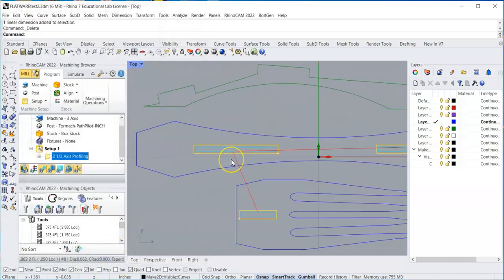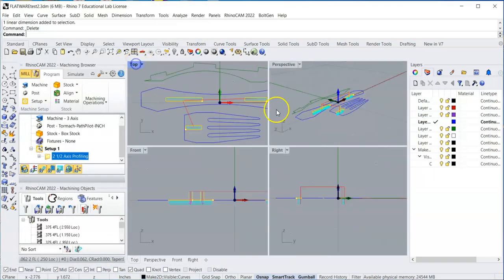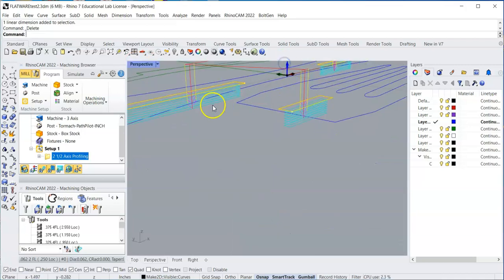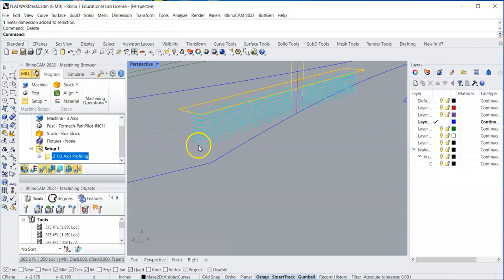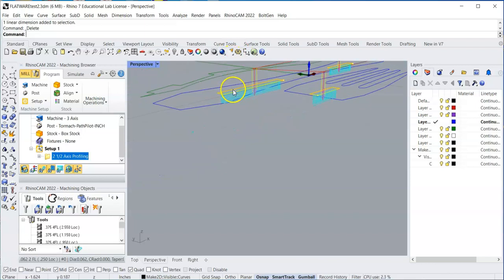And you'll notice it creates a toolpath. And if we look at it in this view, oh look, it arranged automatically. It told us that to get to that depth, we've got to take 1, 2, 3, 4, 5, 6, 7 passes, depth of cut, right? With a 0.02 depth of cut to get through that stock, okay?